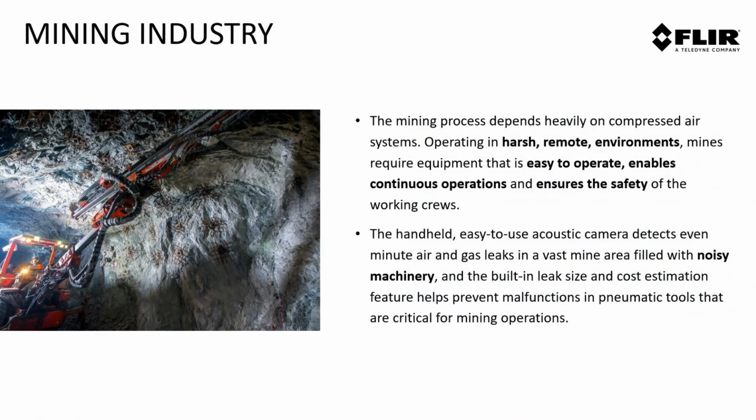On the mining side, not sure how many mining folks we got on the call today, but those are harsh environments. It's very simple to operate these cameras in those environments. A lot of pneumatics are used in the mining space, so be able to identify those leaks quickly, make those repairs, keep those mining operations up and running. And once again, talking about the noise in those environments, being able to do that built-in calculation of those leaks and understanding what's happening is another benefit for that space.